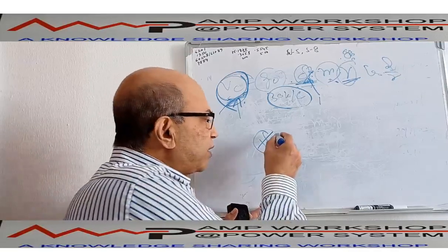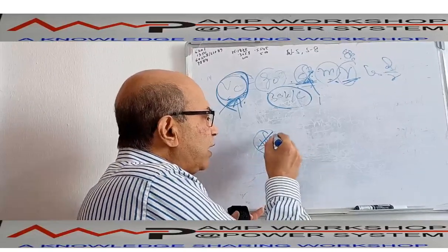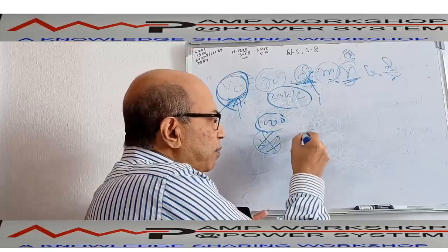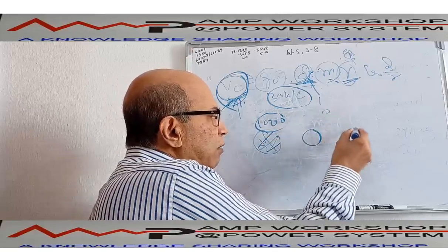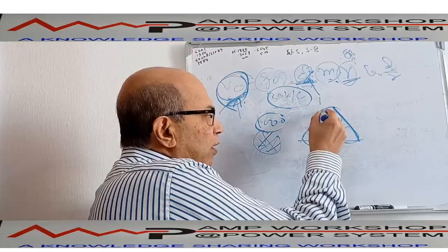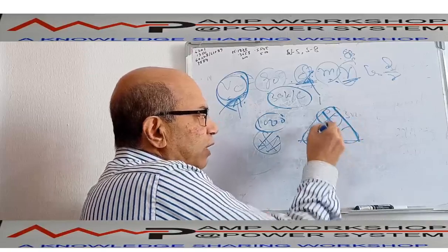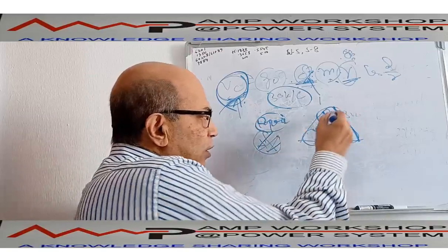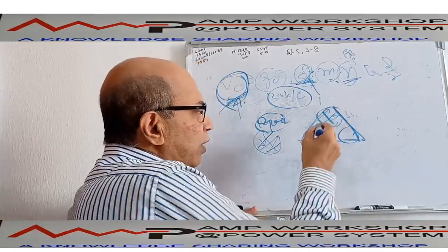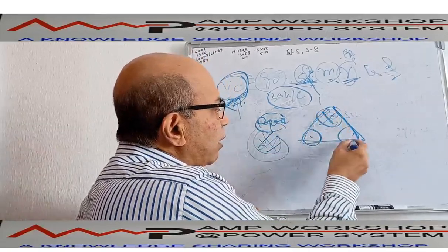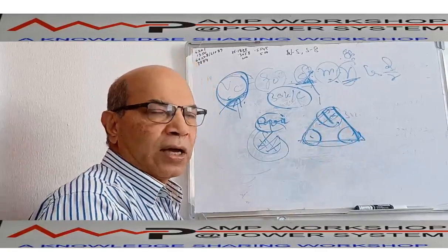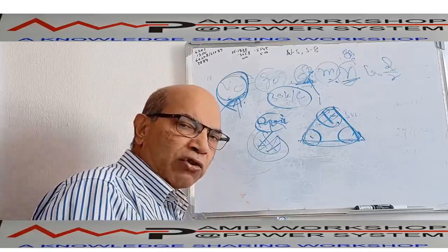instead of a single conductor, suppose this conductor requires 1000 square millimeter. So instead of one conductor per phase, we put maybe 3 conductors, and these conductors are connected through a spacer, and each may be 300 square millimeter. So if 900 is required, we put 3 conductors of 300 square millimeter and connect them with the spacer. So instead of one big conductor, there will be smaller conductors, and these are all the same phase. In that case, corona discharge will be less,